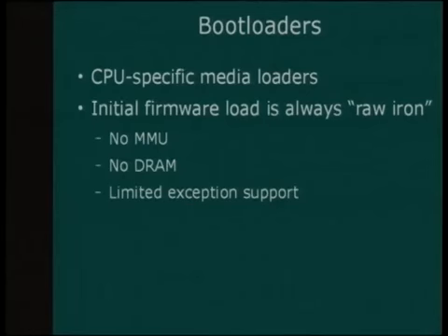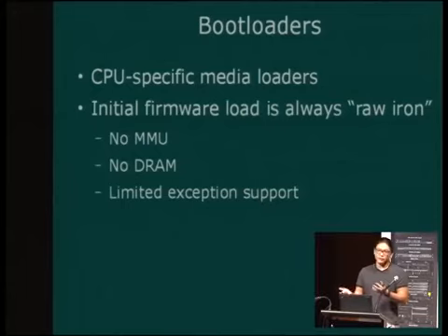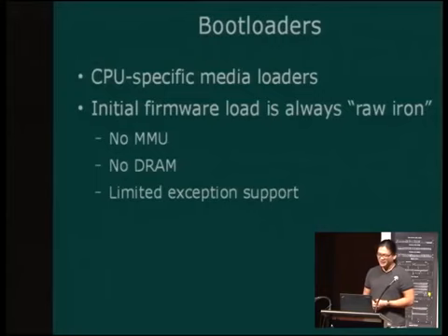Another fun part of getting Linux to run on embedded systems is the bootloader. Every CPU has its own boot process. When we were taught computer architecture or programming, we learned that every computer starts from the reset vector, which is at 0 for ARM. So there's a disconnect between where U-boot is and the reset vector. A lot of people like to think that life starts at U-boot. Actually, life starts way before U-boot.